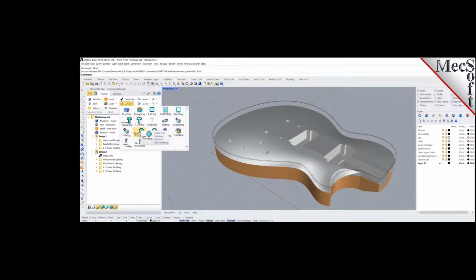But this 2.5-axis, most of you will get if you get the pro product. Hole profiling, hole pocketing, thread milling. We also have T-slotting, and then knife cutting, a tangential knife as well as rotary knives we can use. And then remachining, where you can come in with a smaller tool and machine areas where a bigger tool couldn't get in. So far, so good?